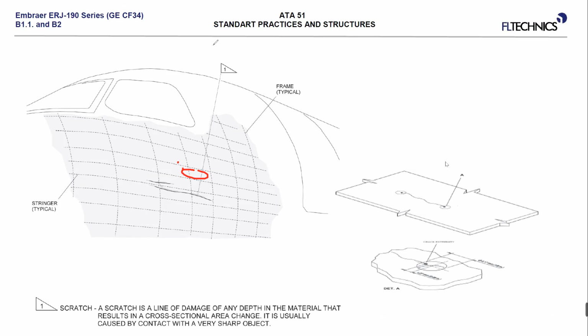Then he came back with one NDT guy, and they measured the thickness using NDT methods, and they found that he blended out too much, and now instead of allowable damage, we have to go to a repairable damage.